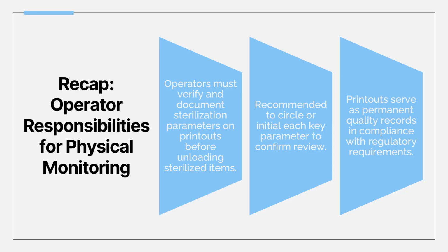So these printouts are actually permanent records. They're required for compliance with standards like CSA Z314 and can be reviewed during audits or investigations. If anything is missing or out of range, the load is considered non-sterile and cannot be released. This step is essential for patient safety and legal traceability, so operators cannot skip it.